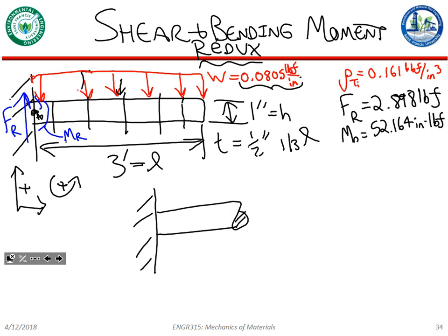But from a materials point of view, we care about the internal reactions all along the beam. We're now very sensitive to how loads are distributed. It's like laying flat on a pond of ice as opposed to standing on it. The stresses depend on how the load is distributed, so we can't simplify that out.